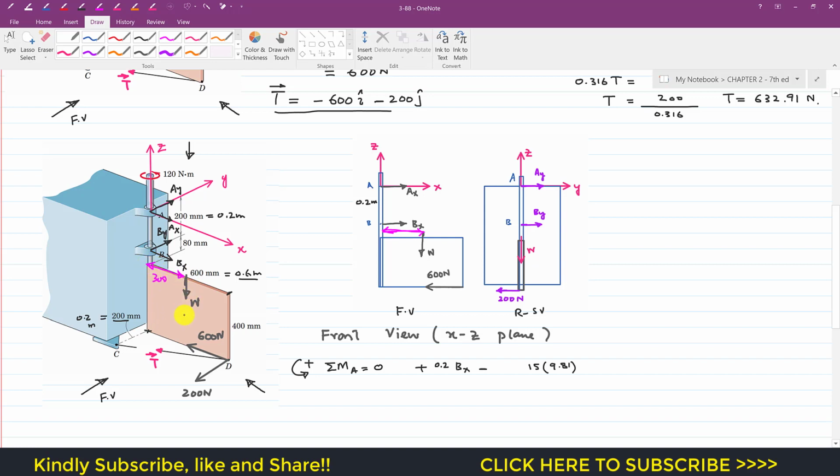Since the weight is going to act at the geometric center of this plate, if it is acting at the geometric center, then this distance will be half of the length of this 600 mm. So this is 300 mm, and 300 mm in meters is 0.3 meters. So we have to multiply this with 0.3. So I will write that this is 0.3 into the weight.